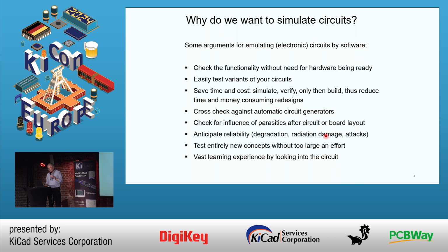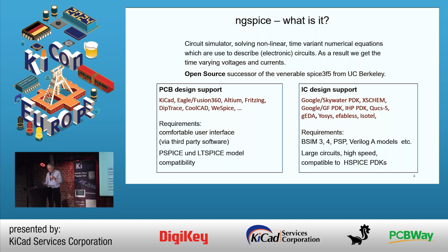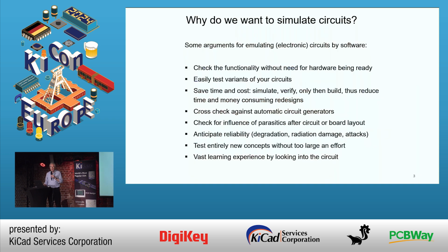You can check for the influence of parasitics. So you do a design, then you have a layout ready on board level or especially on IC level. It's just absolutely common. Then you check for all the parasitics, the resistances, the parasitic capacitances, and then you simulate again and you check if the circuit is still working.